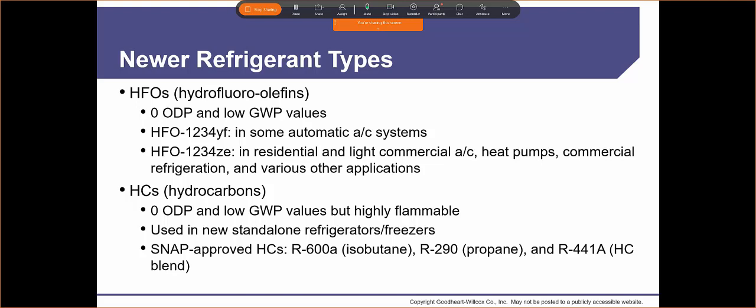Now, what if we have a leak and now our refrigerant is flammable? That's a huge topic of discussion. That's why we haven't really seen some of these flammable refrigerants coming over here. Overseas, they have a lot of heat pumps. They have a lot of ductless systems. So they don't have an open flame like we do with our furnaces, all right? They don't have the ductwork like we do.